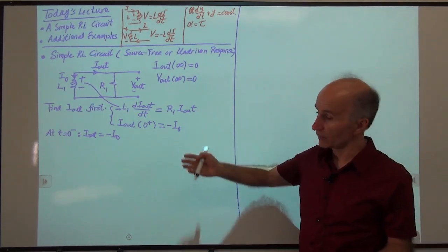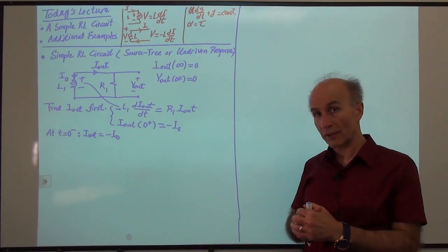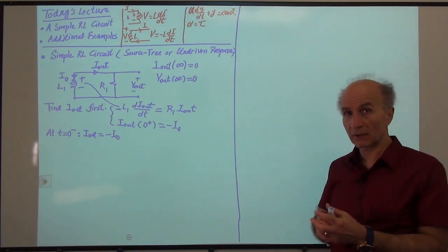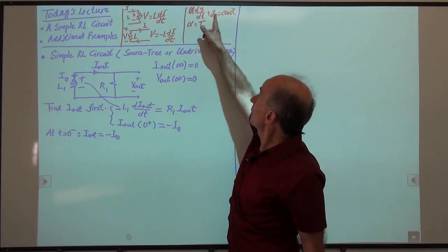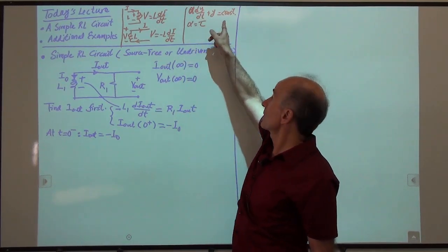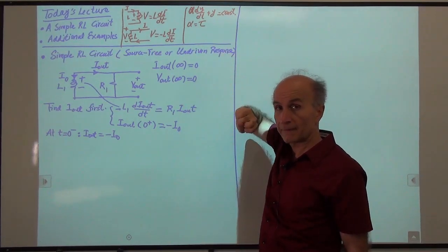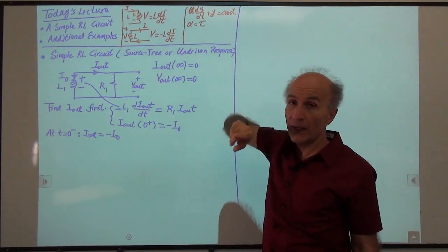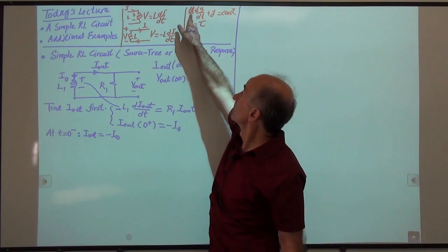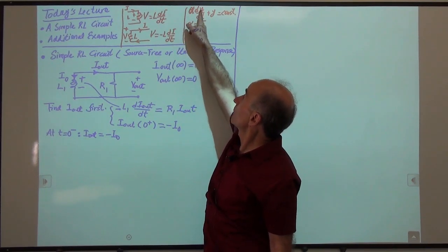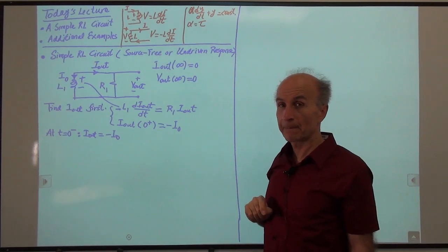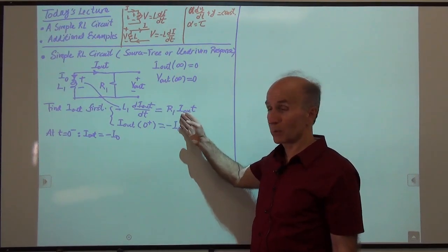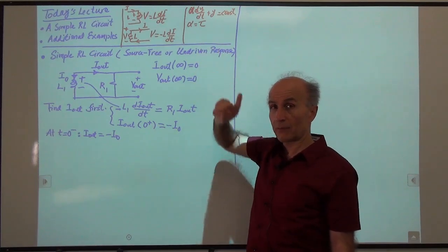All right, so now we can solve this equation. It's pretty simple. It's very similar to what we did for RC circuits. But actually, it's even simpler if we go back to something that we learned a long time ago. If I have a differential equation of first order like this, where the other side is constant or a step function, either way, and the coefficient of y is 1, then the time constant of the circuit is given by alpha, the factor that comes before the derivative with respect to time. So I can quickly predict the time constant of a circuit from this differential equation. I just have to write it in that form very carefully.